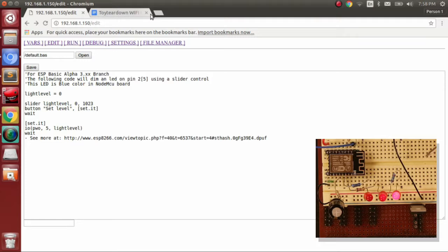What I've learnt with this unit is the most important thing is to have a dedicated power supply. I've spent countless hours trying to fault find this without a dedicated supply. I used one from an Arduino and it was bizarre. It would work for hours and all of a sudden all sorts of weird things start happening, so a must is a dedicated supply. Also pull-ups on the reset pin, the chip enable and the GPIO0 as well for more reliable operation.